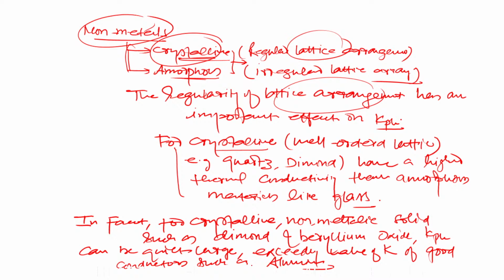The effect of temperature on the solids is clear. In the case of metals or electrical conducting materials, where electrons are present, K decreases with increasing temperature, because flow of electrons is the dominating mechanism, which is going to be hindered by the effect of lattice vibration at a high temperature. That's why K of metals will decrease with increasing temperature.